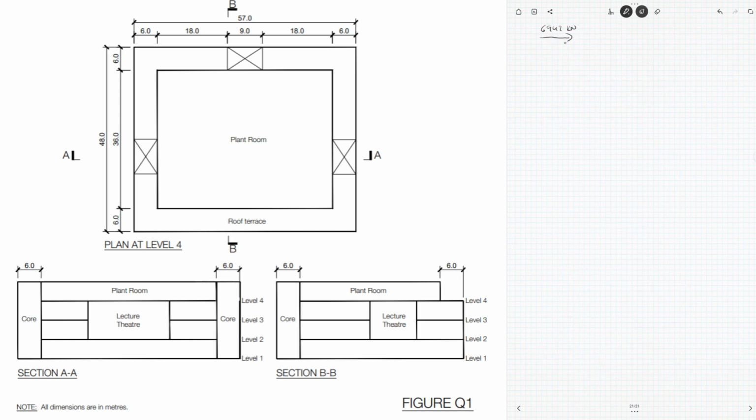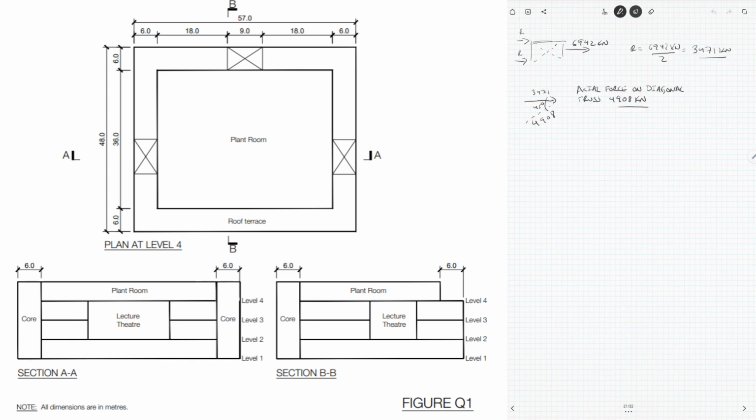First one is doing calculations of regular members rather than singular or main structural elements. So anything that is regular members rather than singular structural members, you should just size them with span depth ratios like beams and columns, etc. Just use tables if you need to.